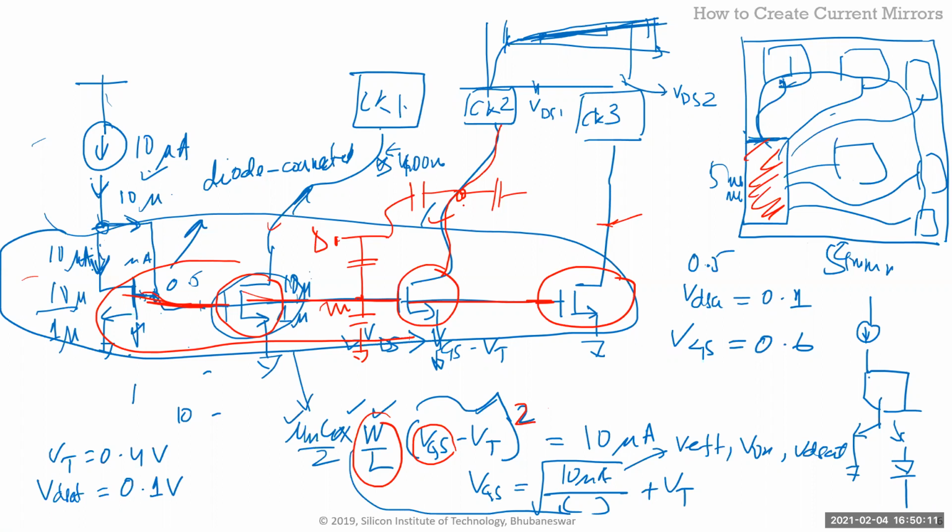If I change the drain voltage of a saturation current transistor, how much does the current change by? Let's say lambda was equal to 0, ideally. How much will the current change by? Nothing. If lambda is 0.01, then it'll change by 1%. Whereas if you change the gate by 20 millivolt, it'll change by maybe 10%, 20%, depending on what it is.